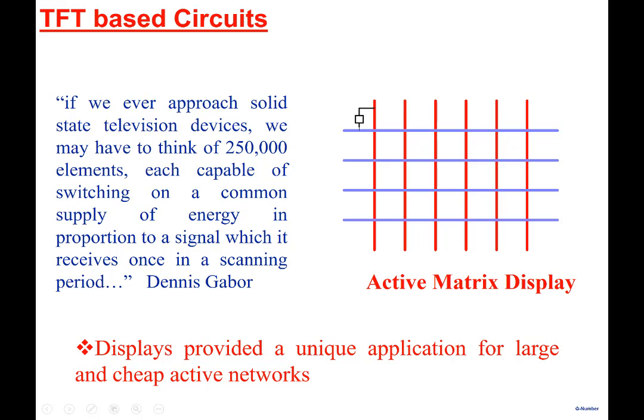Because of high resolution, we'll look at some numbers, the size of the switch is small, and therefore you cannot take a packaged MOS transistor and solder it there. You can't do that. You'll have to manufacture it on the glass itself. Okay, so that's why you would require TFT on glass.